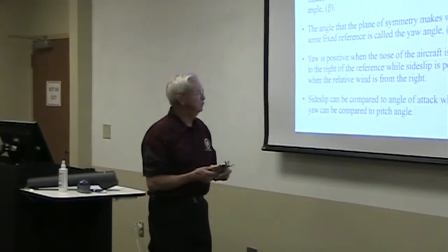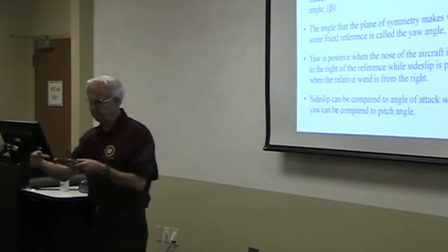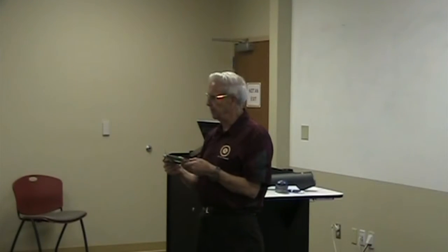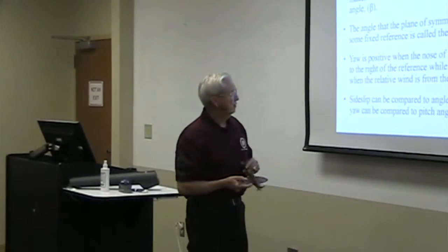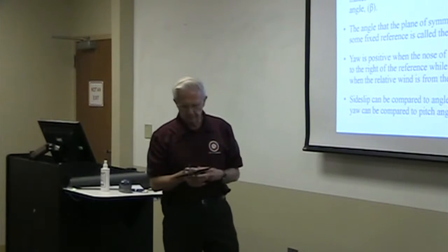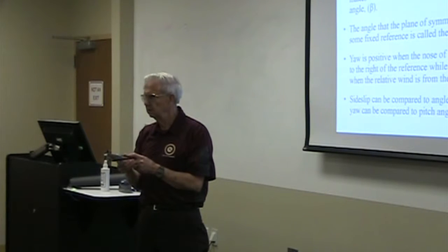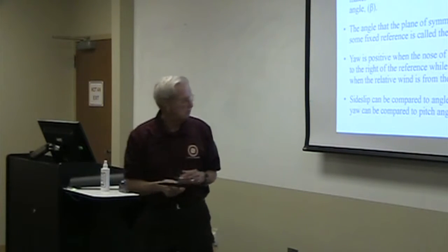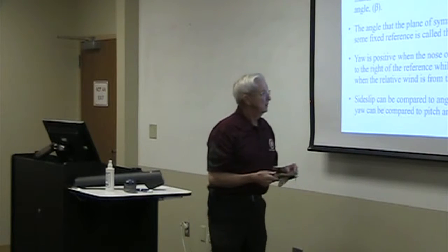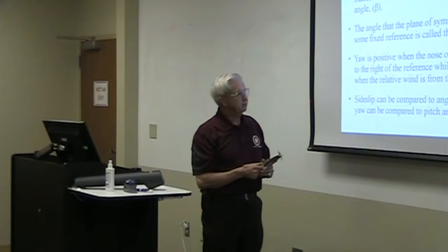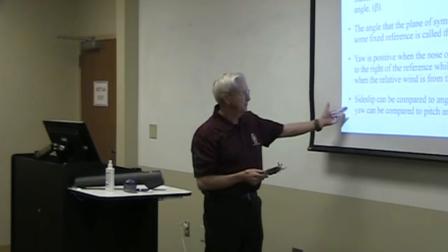So yaw is positive when the nose is moved to the right. We said wind blowing from the right was positive side slip. Well, when the nose moves to the right, it's positive yaw angle from that reference. And a lot of times we just say our initial heading is the reference. And so if the nose moves to the right, that's positive yaw angle.